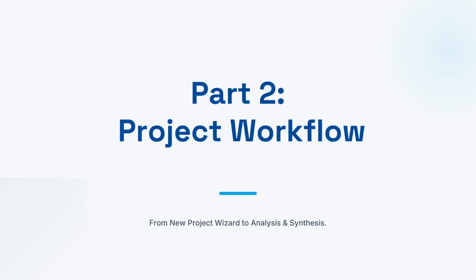Now that our environment is ready, let's step through the standard design flow. We will initiate a project, write our first lines of VHDL, and talk about mapping virtual signals to actual copper pins on our development board. And I am using the DE0 as an example.